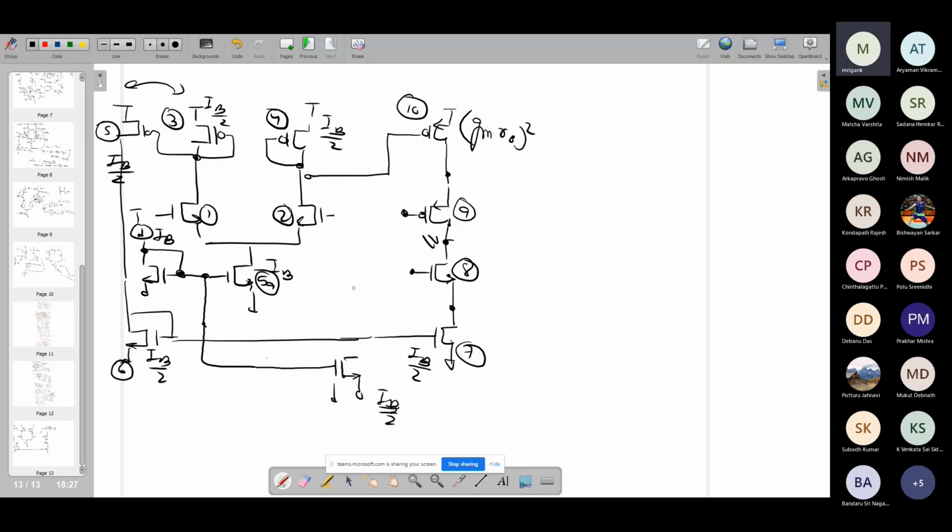And then I need to have an NMOS stage where I can basically just have a diode connected connection, and on the top of that we can also have a PMOS with another diode connected connection, and following that maybe we can also have another PMOS with a diode connection.